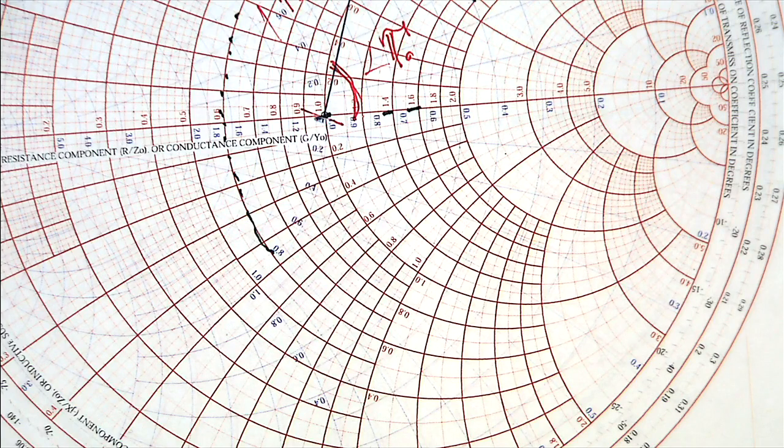The same thing we have for the short circuit transformation. Again, a transmission line with the length of L, if I terminate it with a short circuit, then Z in equals J Z naught tan of beta L. We had this in the previous lecture.